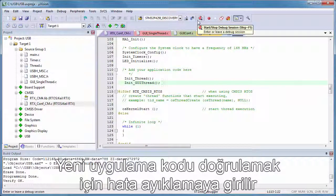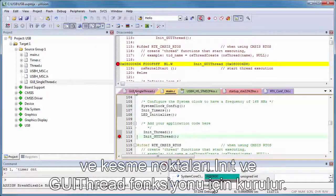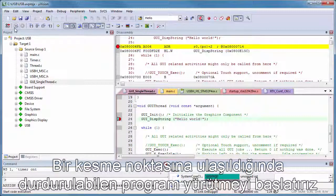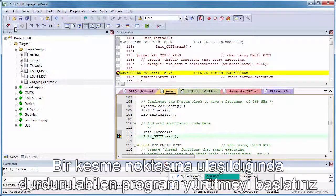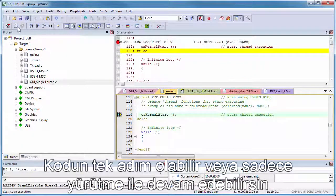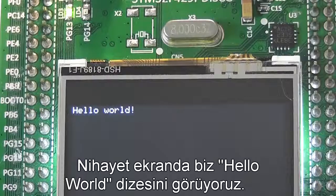To verify the new application code, enter the debugger and set breakpoints to the init and GUI thread function. We start the program execution, which is stopped when a breakpoint is reached. You may single step the code or just continue with the execution. Finally, on the display, we see the string Hello World.